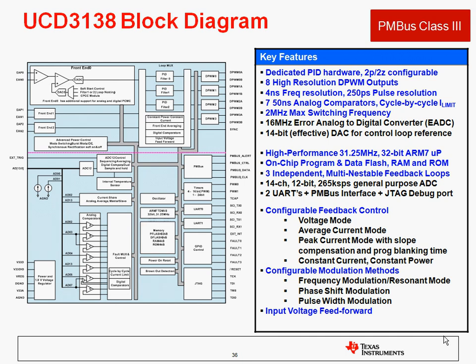And this just shows you what it looks like inside. There's a number of hardware blocks up here on the top that will be your standardized power function blocks that need to be fast, they need to be precise, and then below is a full microcontroller based machine that is fully programmable and has a number of different interfaces, so that you can program it and/or monitor it through a number of different interfaces, such as UART, PMBus, and JTAG.